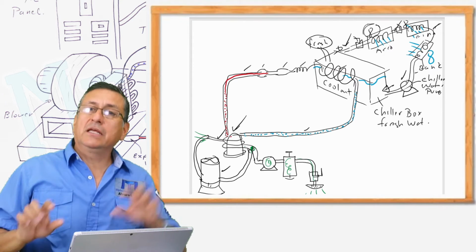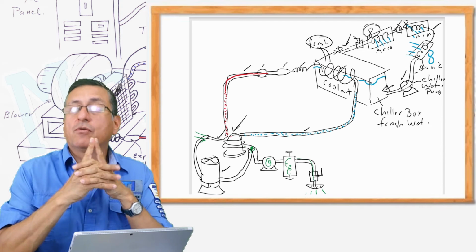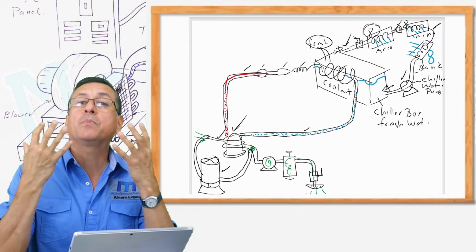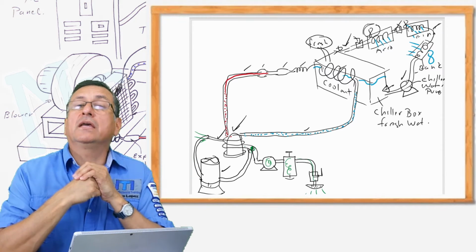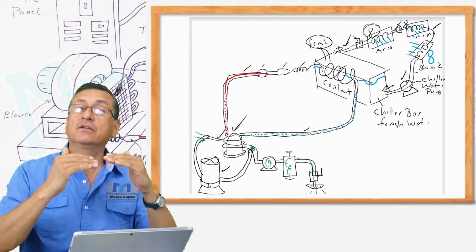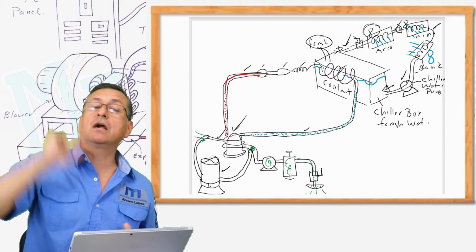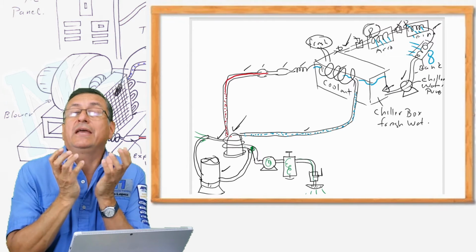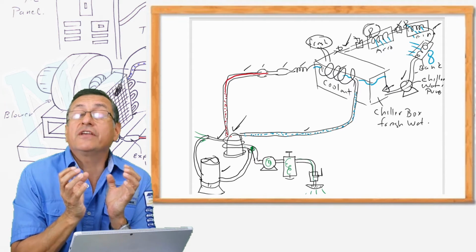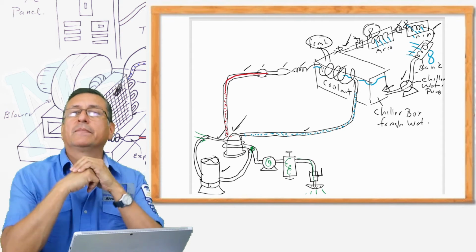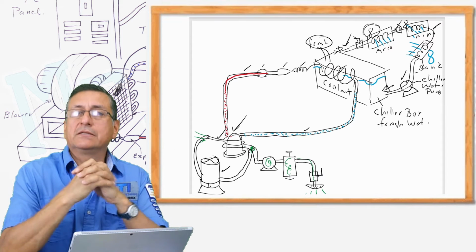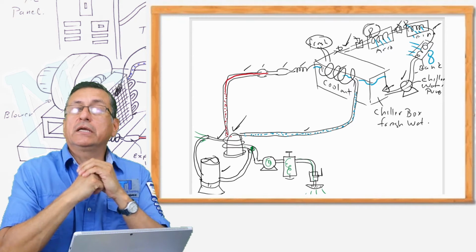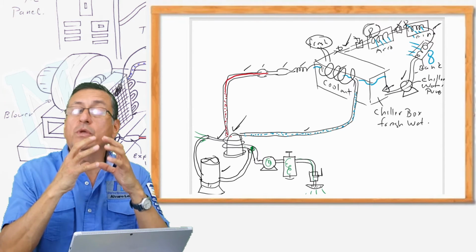Yes. In the air handles, the majority of the equipment doesn't use traditional fresh water. They use coolant. What is the purpose of the coolant? It is because the freezing point is lower and the boiling point is higher. In this particular case, we are focused on the freezing point, the lower point. Yes, this is the liquid used in the air handles in the chiller systems. It's a glycol with water.